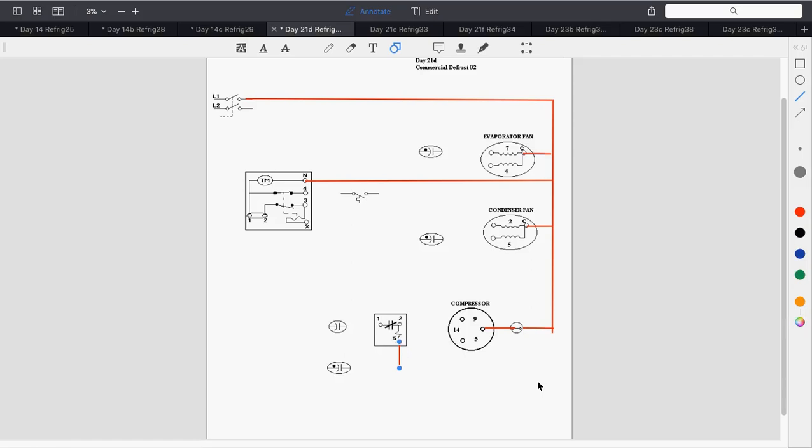To the motor side. You're going to see it both ways, but the way it should be is on the motor side. The reason is if you have a power surge that opens this overload, we want this relay not to get an energy difference across that overload. So I want to take it out. I don't want this coil to be powered. Again, you're going to see it both ways, but the recommendation is to do it this way. Let me just make this neater for you guys.